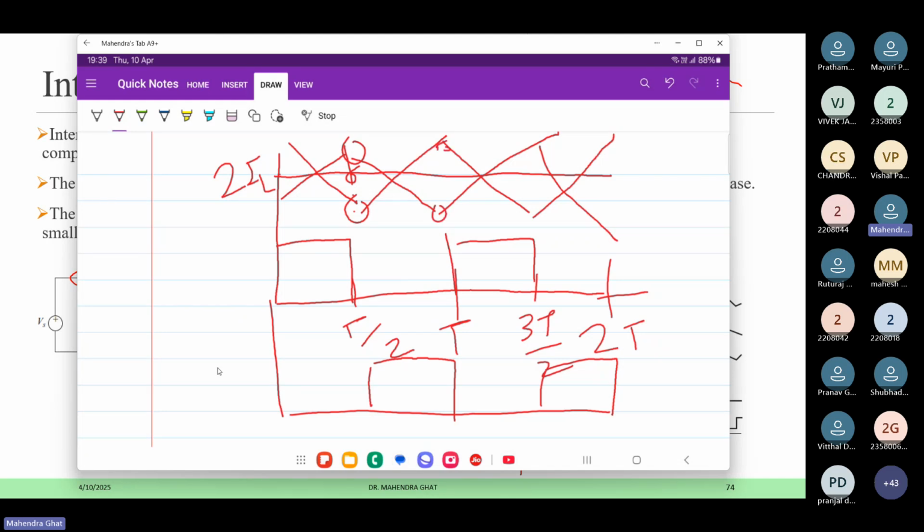So they will cancel each other, and you will get a very constant current at the output. Okay, so at 0.5 duty, you will get exactly constant current. There is no ripple. For other duty, you will get lower ripple as compared to the individual, and at 0.5, you will get no ripple in the output. So the ripples are getting cancelled by each other.